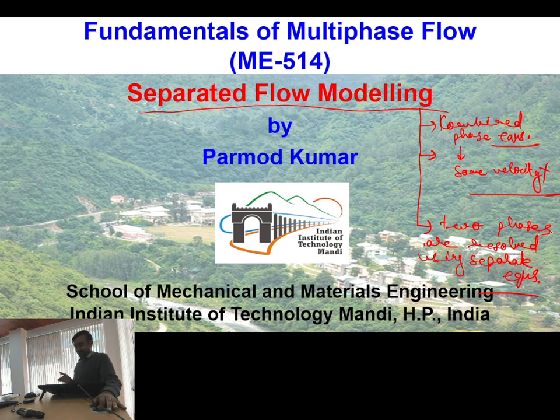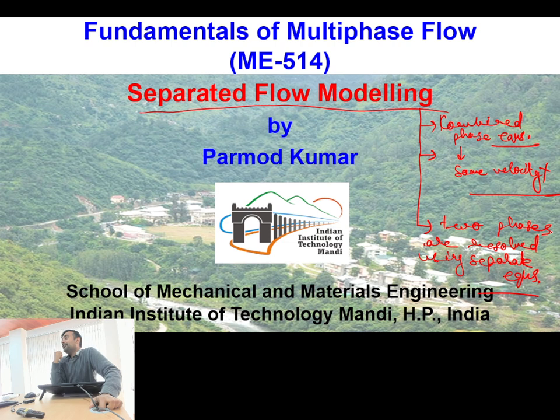Okay, but doing this exact separated flow approach is actually very, very challenging, because so many interaction terms are involved, and the value of these interaction terms depends upon the spatial phase distribution. Because if you have some interface between the two fluids, then the interfacial force exchange and the interfacial momentum exchange are all to be accounted for, and only then can you use this approach completely. So that's why this second strategy is actually more cumbersome.